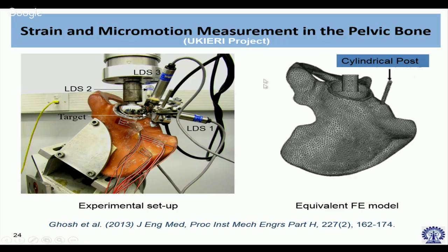Okay, this is the equivalent finite element model that we generated. Remember, you have to reproduce the testing conditions exactly in this FE model, okay? Otherwise, you will obviously get deviations. It has to be absolutely the same.